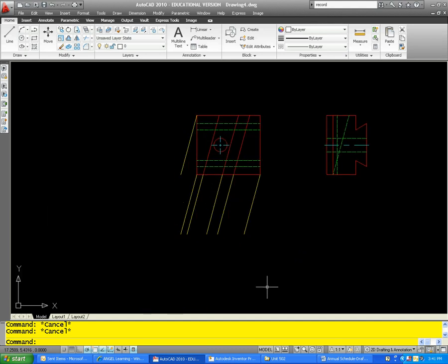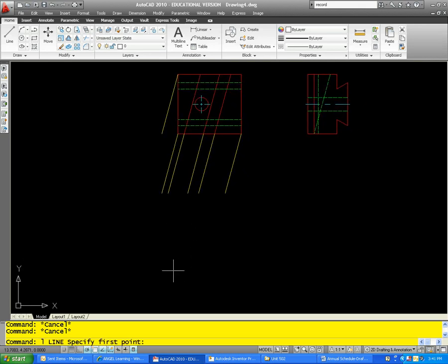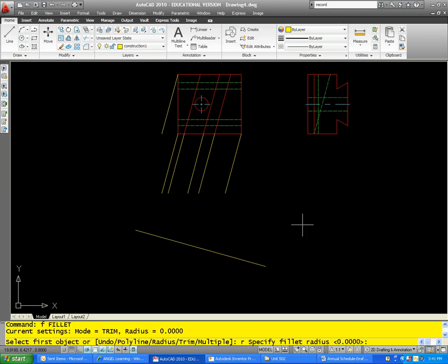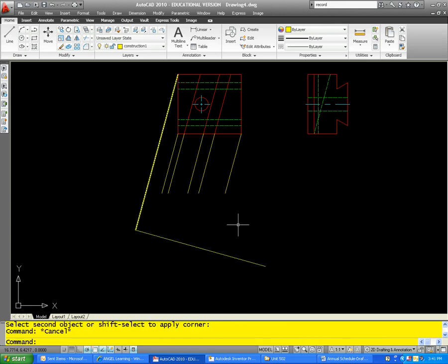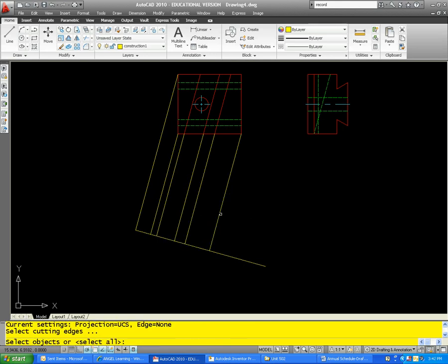but to be able to answer the questions you need to project in this direction as we're doing here on the video. So let me do LPER for a perpendicular line, and then FR0, and then I will extend those other lines and trim off the excess.